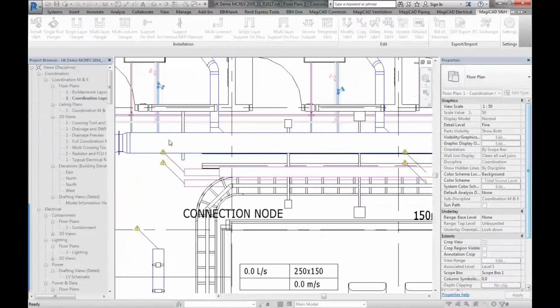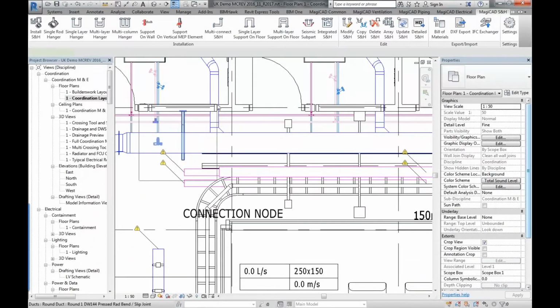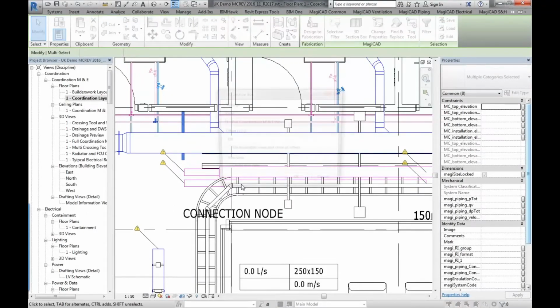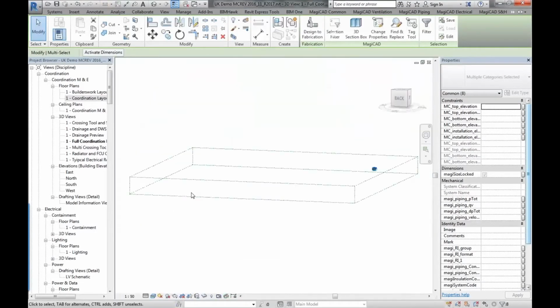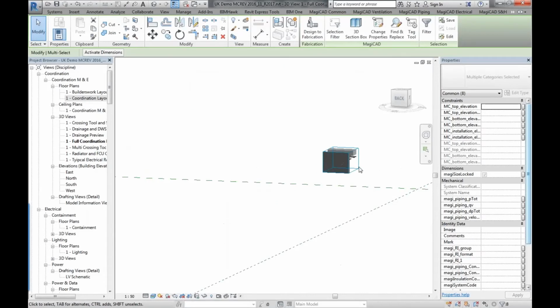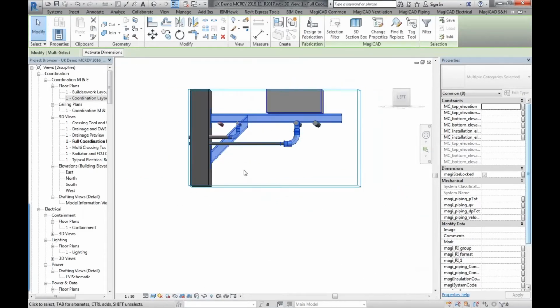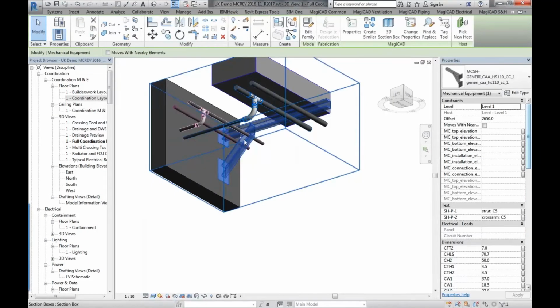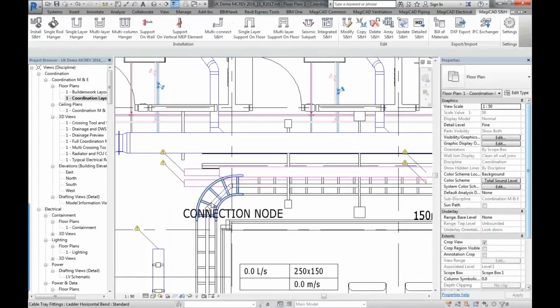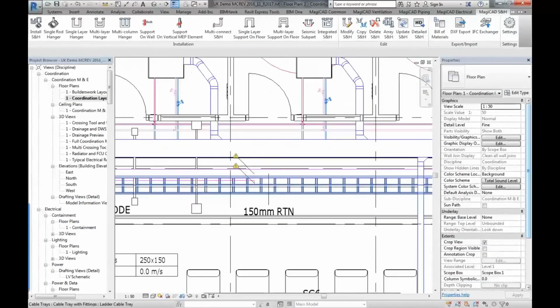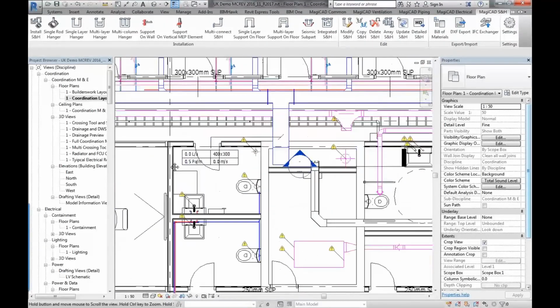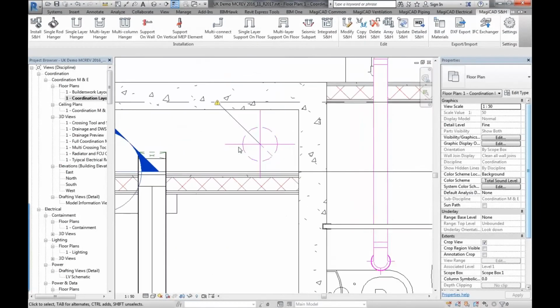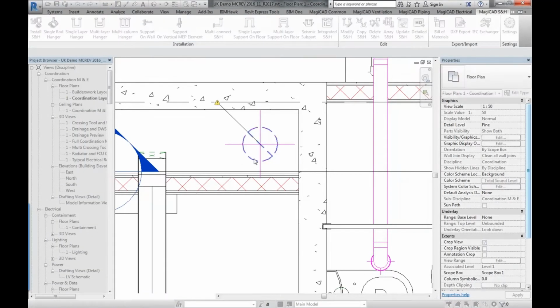When you get the specification that you want for the steelwork, once you press OK, it'll just create the hanger just like everything else before it. So you'll see now it's got the support on the wall. If I just quickly go into that 3D view, you see how that works there. You can see the cross member there on that beam. So that's that one.